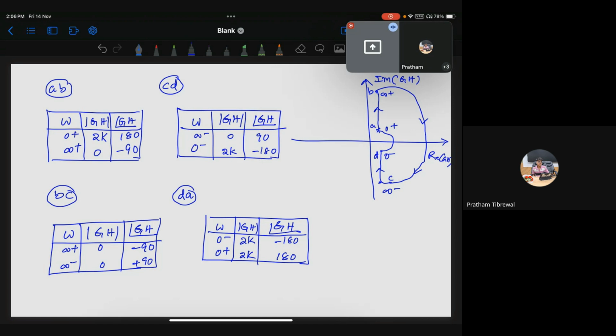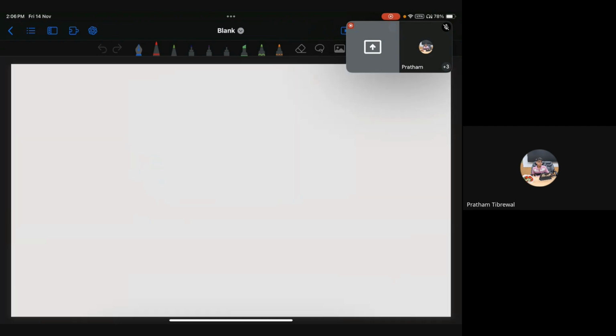Then, if you see this Nyquist curve, it is not that everything stays on the right side. This is just the Bode curve only. The plot can be on the left and right side also, based upon the given transfer function. So for that reason, first we want to check where this plot is intersecting with the imaginary axis, and where it is intersecting with the real axis.